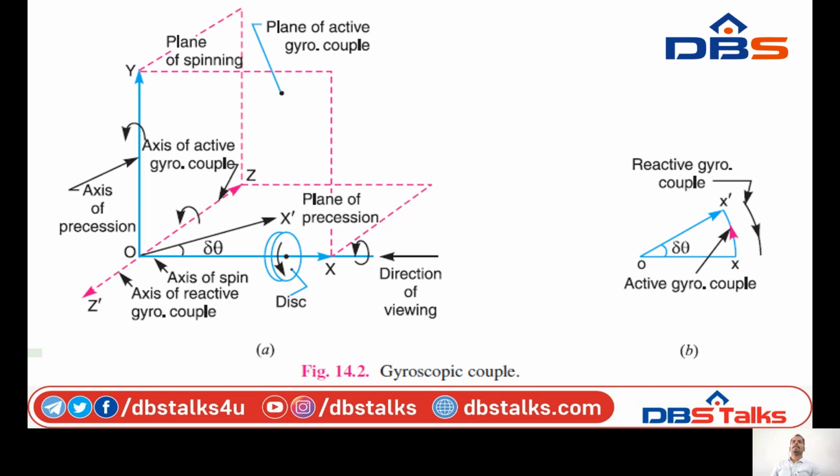The axis of spin OX is also rotating anticlockwise when seen from the top about the axis OY. Let the axis OX be turned in the plane XOZ through a small angle delta theta to the position OX dash in the time interval of delta t. Assuming that the angular velocity omega is constant, the angular momentum will now be represented by the vector OX dash. So with that we get the change of angular momentum.